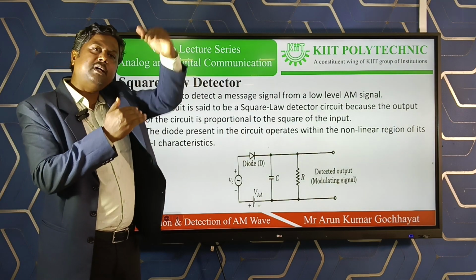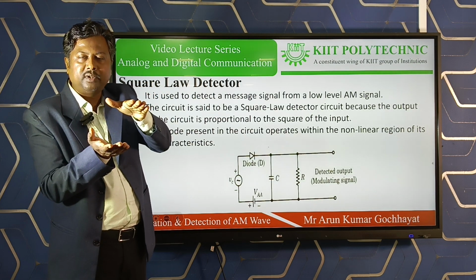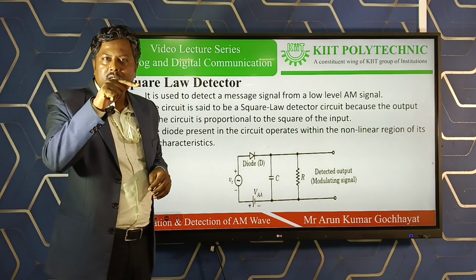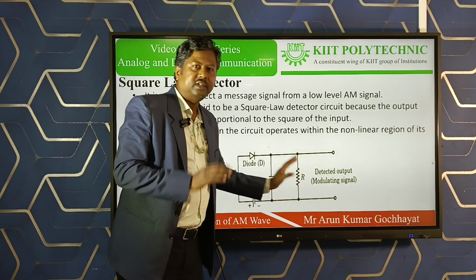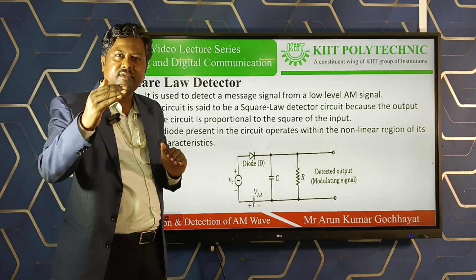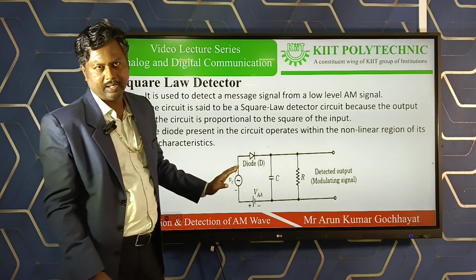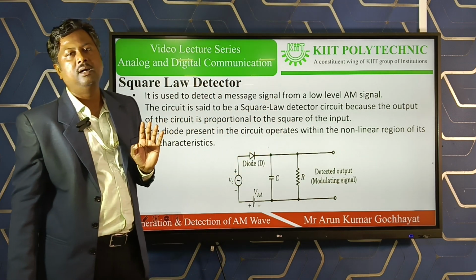But if the positive half gets expanded and the lower negative half gets compressed, then the average value becomes sinusoidal in nature. So this output, that is the average value of the lower and upper halves, is sinusoidal in nature, and that is nothing but the message signal.